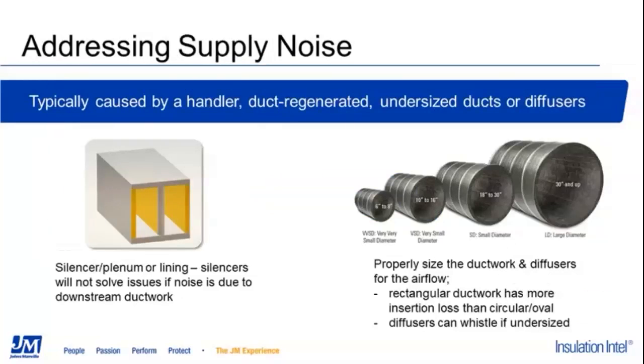And similar, we have supply noise. So this is noise specifically traveling down the duct. This is caused by noise from the air handler itself or possibly due to regenerated noise from components that are downstream from the air handler. So air handlers are notorious for developing low-frequency noise that's really difficult to mitigate. Using silencers and plenum boxes are pretty good tools to deal with this.